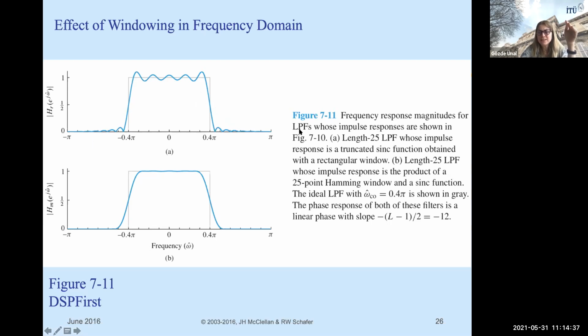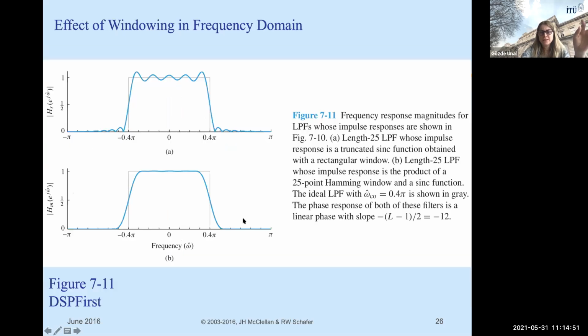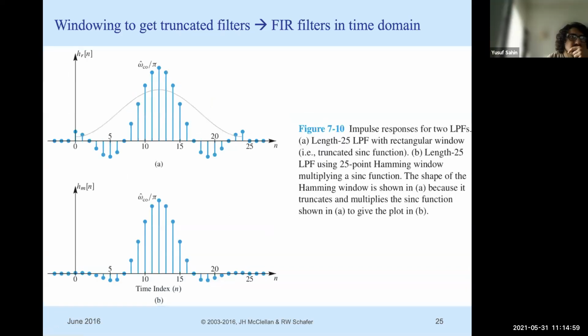So what we did, guys, is we took the discrete time Fourier transform of this truncated filter on the bottom, to obtain these two frequency domain responses of practical low pass filters. Okay, so you see, by the way, these have become FIR filters, finite impulse response filters.